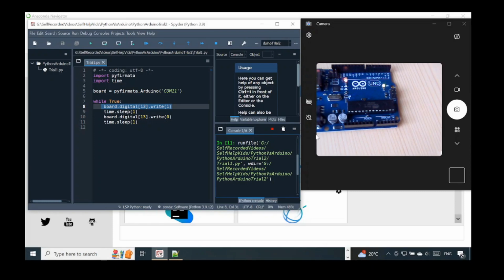So that's the end of the introduction on how to communicate with the Arduino board using a Python script on the computer. This way we can connect some sensors to our board, collect data with our Python, and start to process that data in Python. I think it's more friendly and more convenient to process the data in Python rather than in the Arduino platform code.